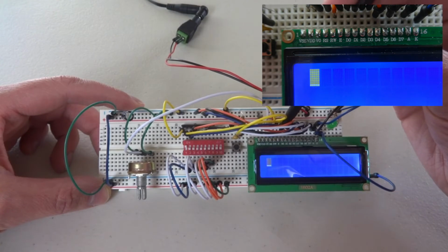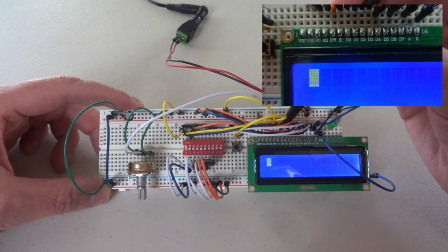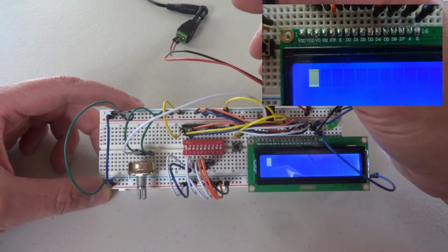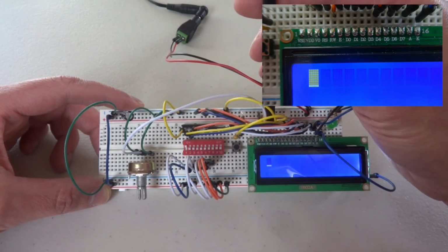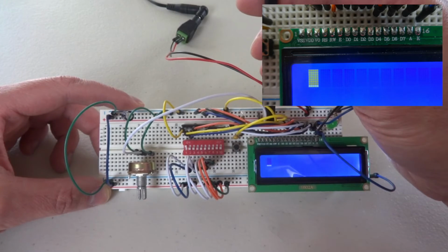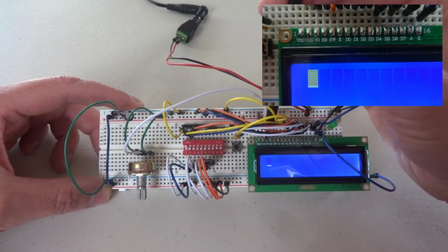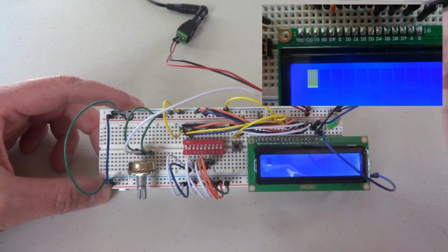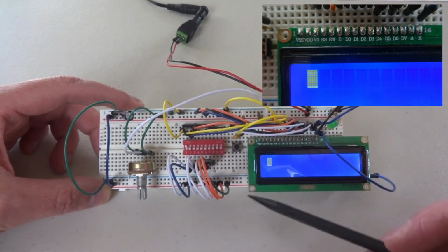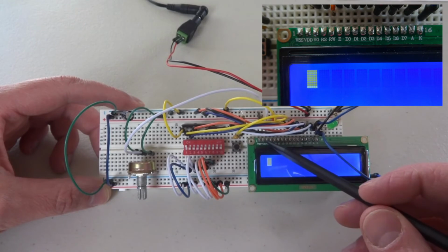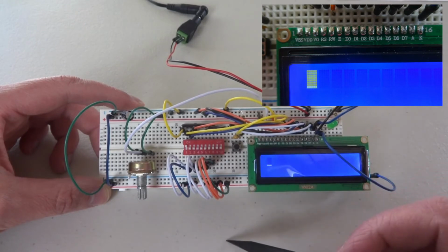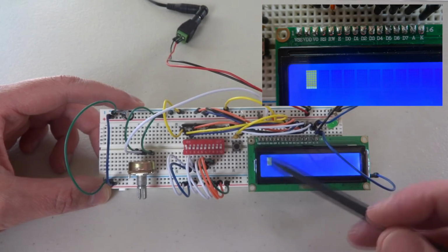When we send characters to it, we convert the ASCII to binary and send data to the pins. There are lots of handy web pages online that will do this conversion for us. We'll demonstrate that in a few moments. Now the E pin starts data read and write. This is connected to our button. Our W is to set whether or not we're reading or writing. We're only going to write to the LCD. And then RS is the register select pin.